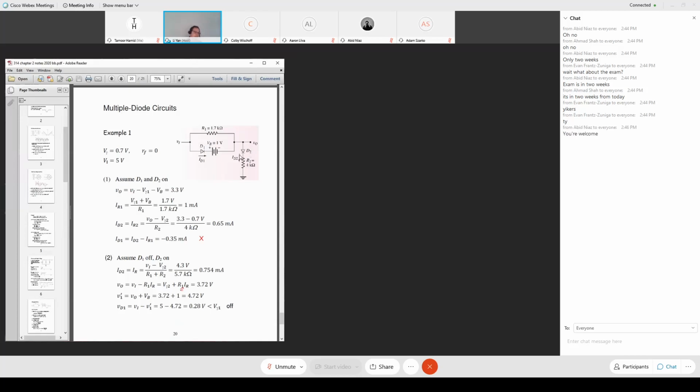So D2 should be forward bias. Likewise, D1 is forward bias. You may say you're putting a battery there, but qualitatively speaking, you have 5 volts here, you have 1 volt there, this side looks like it's still higher. So my eyes tell me, qualitatively, both sides look like they're in the configuration of forward bias, not reverse bias. So if you previously thought both sides were under reverse bias, you have to figure out why you concluded that way. That was incorrect. What that means, qualitatively speaking, where's the high voltage side, where's the low voltage side?